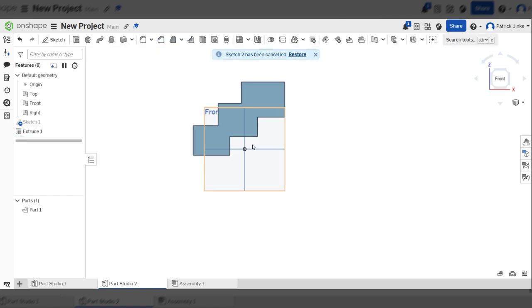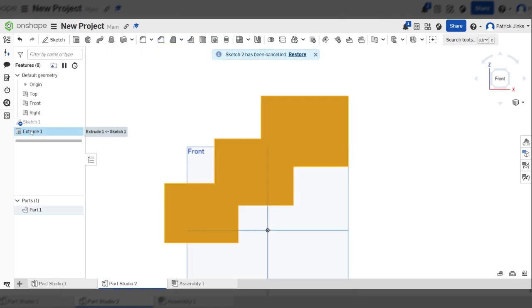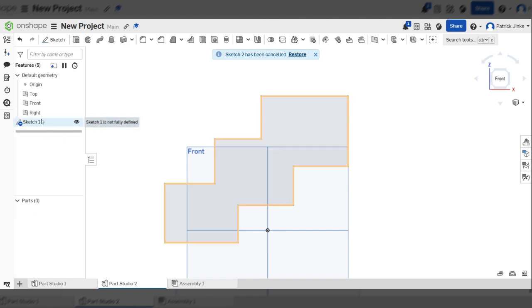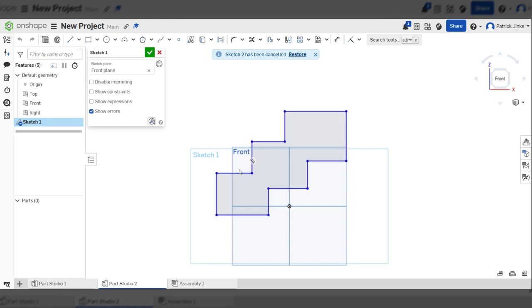Okay, there's one other thing I'm going to show you. I know I said there wasn't. I think this will be a good thing for you to see. Let's take the stairs again. I've decided I want my stairs a little bit bigger. But if you've already dimensioned it, it's going to be a real pain to redimension it and make everything 5 mil larger. That's why we've got the offset tool. The offset tool is next to the trim tool on my toolbar that we've just used, and I'm going to use this to make a border or an outline that's either bigger or smaller than my piece.